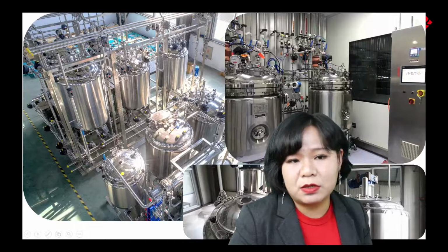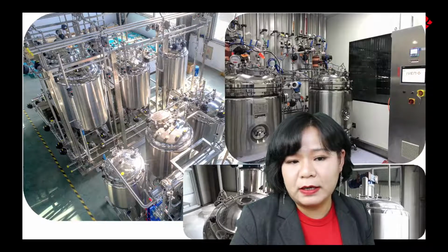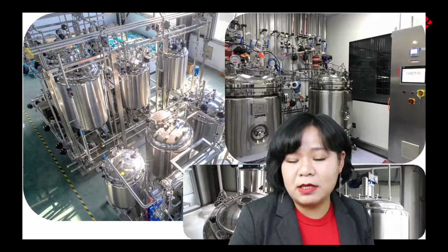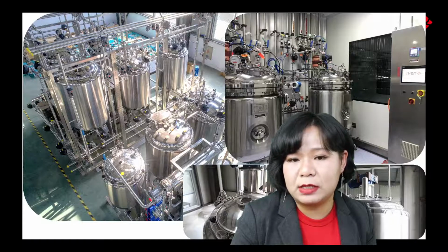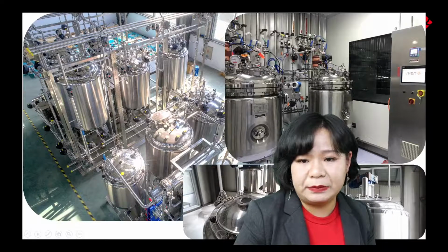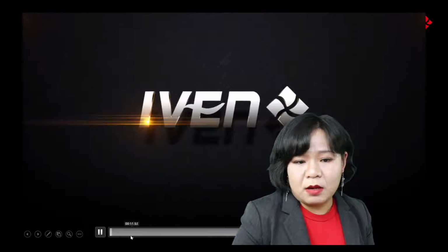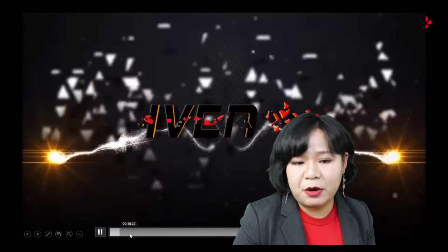And also make sure there's no dead corner inside, and make sure the flow speed in the whole pipelines meets the current GMP or USP or the EU. Okay, we have some video to briefly show you around in our factory.